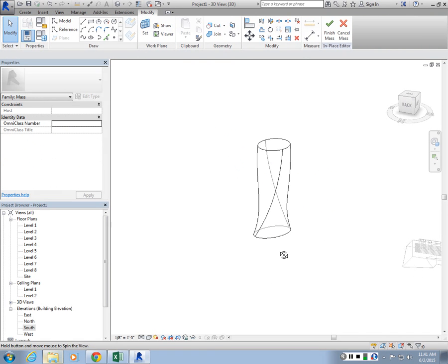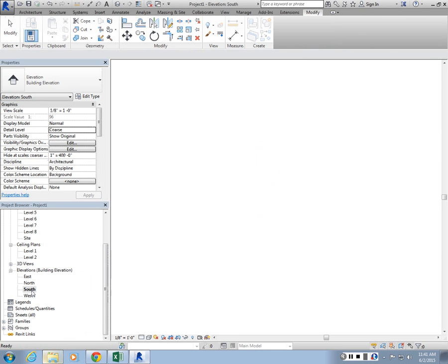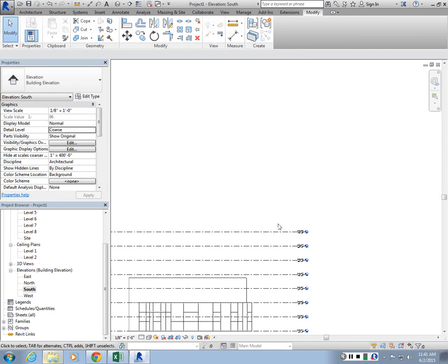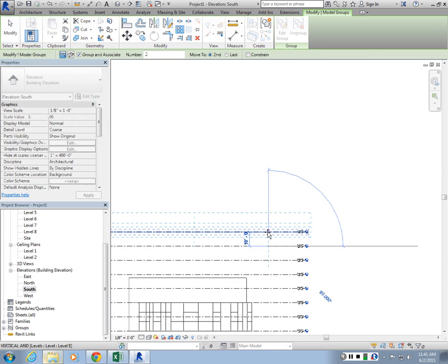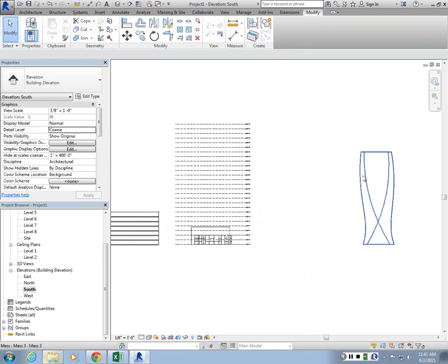It's like a nice glass, right? So I'm going to finish the massing, and the same thing. I could extract the floor plates from it, but you need to create a level for it. So I can make another array. Let's say 20. I'm going to create 20 more levels.